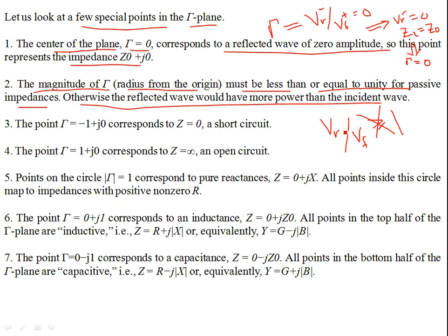For an infinite standing wave ratio, there is no transmission being done, so the transmission S parameter will be small because all the wave is being reflected back. But the reflected wave can't be greater than the forward wave.